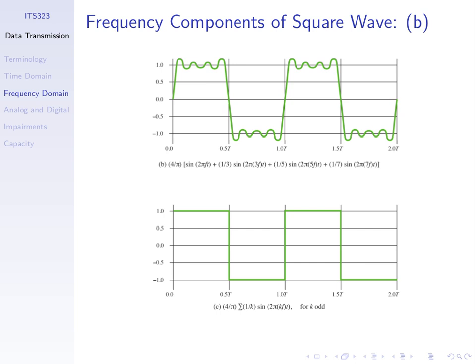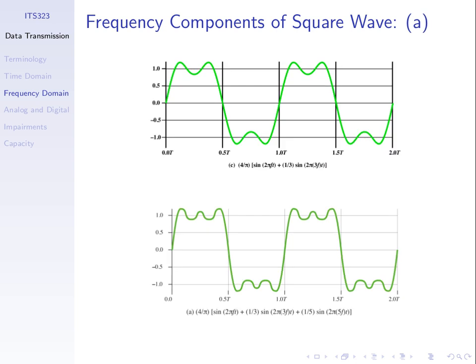We could also use the signal above it to transmit the same sequence, because it also has this pattern of high, low, high, low. In fact, we could use any of these to represent the same sequence of bits. The communications designer needs to choose the best signal which meets their requirements, which will depend upon data rate, bandwidth, and one thing that we cannot calculate but we'll talk about, which is accuracy of the signal. We'll come to that as we go through the example.